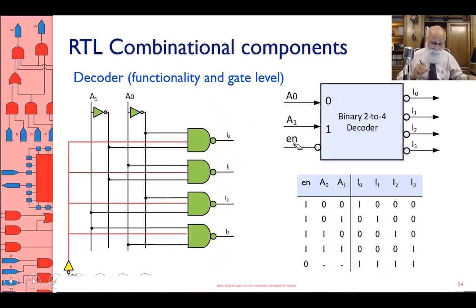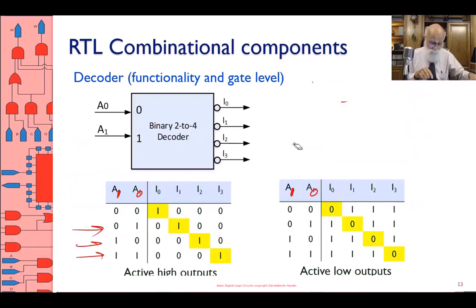The thing is, if I were to build this, which I'm going to be doing right now, the gates that are available to me are NAND gates, NOR gates. Okay, let me go back to this slide here. So if I start building this, I say, well, okay, let's put A1 here, A0 here, and let's put 2 inverters here.